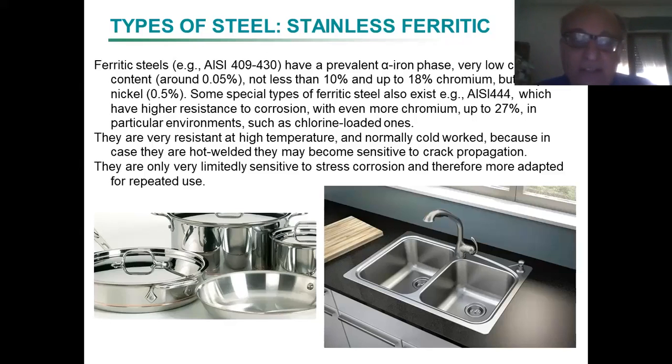Then there is the main question of corrosion, which we have treated last time. Corrosion doesn't tend to be a big problem in ferritic steel, unless there are environments in which there is lots of chlorine. This can happen at sea, or this can happen by treatments which are required, especially alkaline treatments, like with sodium hypochlorite,